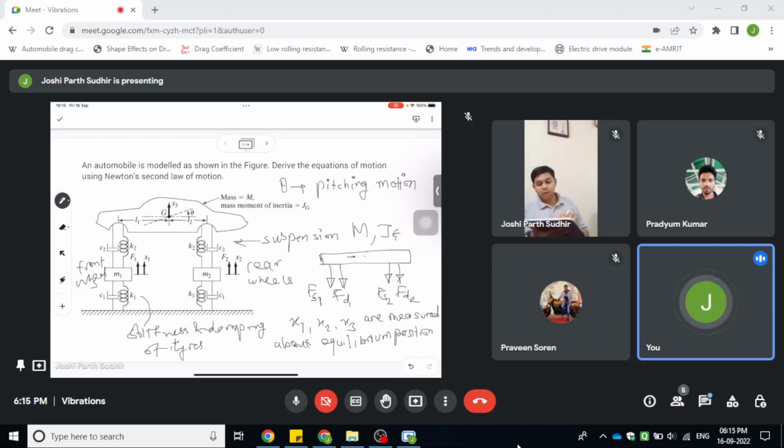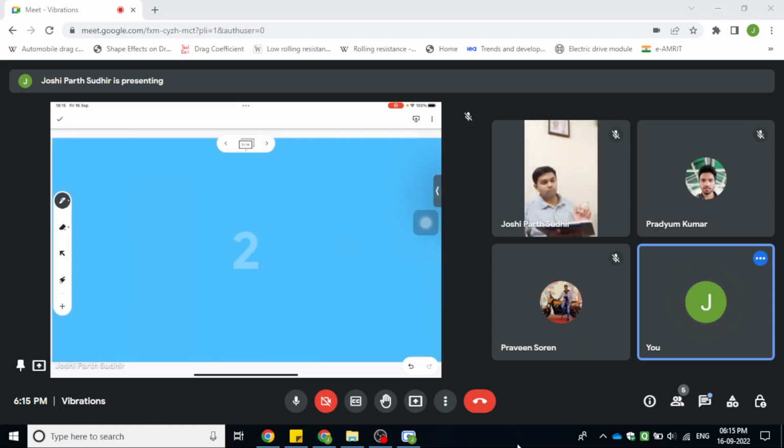So then that will eliminate the weight. Then weight does not become a dynamic force, and we can just ignore that while writing the equations of motion. We can actually prove that mg, the weight, will not be a dynamic force by selecting absolute coordinates and then converting them into coordinates which are measured relative to the equilibrium position, and then we will get the same thing.